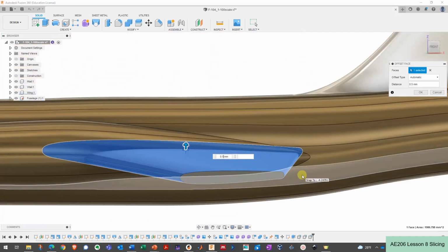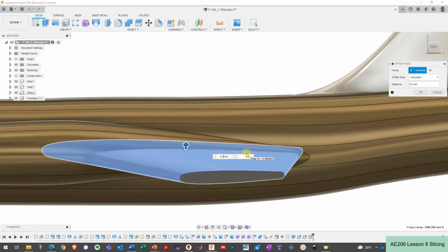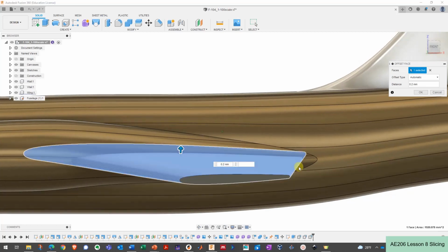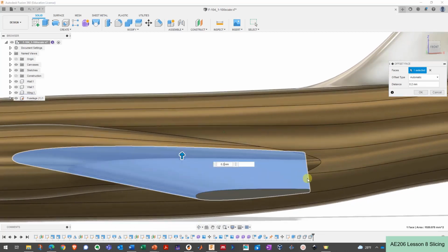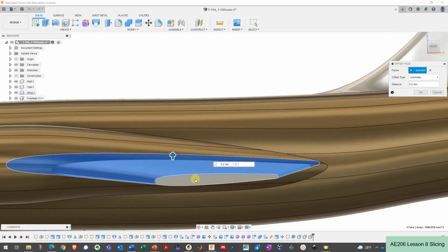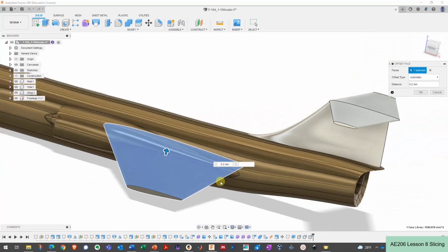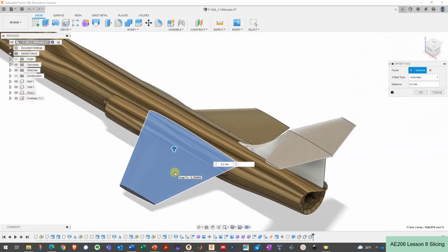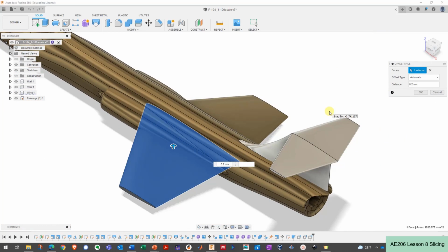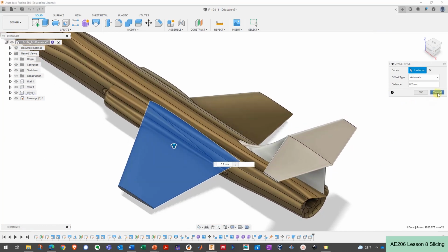Now we're losing part of the wing shape here, that's for sure, but I've kind of exaggerated how much thicker we need to make it in this case. In this case, I only had to make it 0.2 millimeters thicker, which was 0.4 on both sides. And this actually still looks pretty airfoil-ish and results in a successful print. So this press-pull tool and making your wing a little bit thicker is the first solution that you should try for that thin part problem.